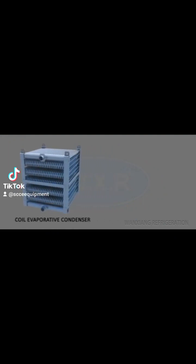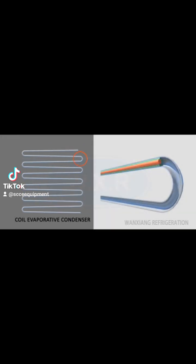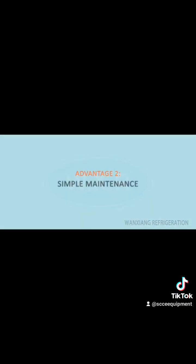In the case of conventional tubular coil evaporative condensers, the cross-sectional area available for the hot entering gas is relatively larger. This results in lower gas velocity, which is unable to maintain a uniform annular film along the tube periphery, and therefore very early along the flow path, a separated flow is formed with condensed liquid occupying the lower section of each tube, and therefore results in lower overall thermal performance. The same is true on the water side. The longer distance traversed coupled with gravity effect, so the water flow distribution gets uneven, and thus results in lower performance.